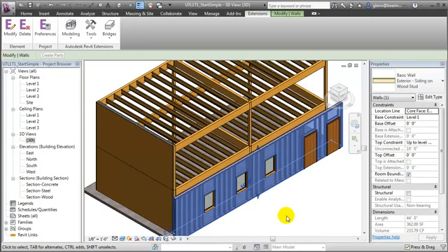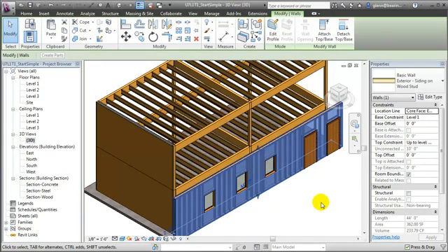You'll see that the extension has adjusted the height of all the framing elements and made allowances for the window and door openings. There are still a few missing pieces above and below the window openings, so we should return to the wood framing extension, adjust the settings, and specify how we'd like to handle the framing in those conditions.